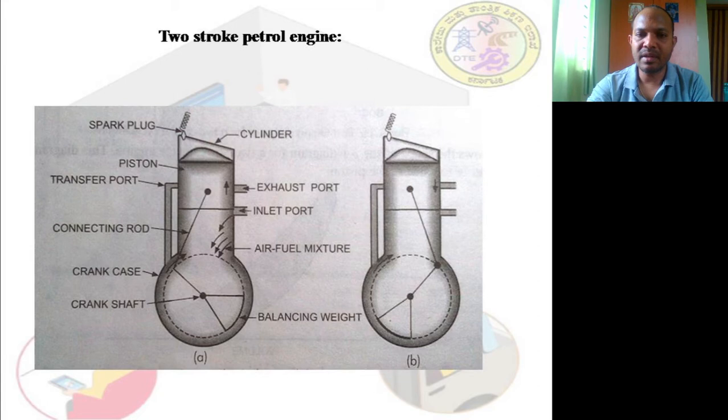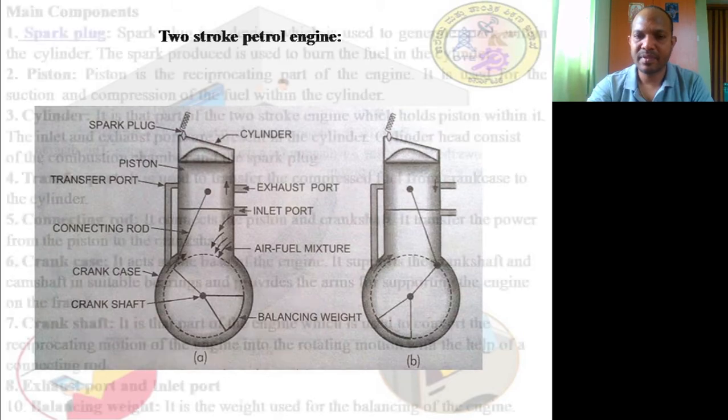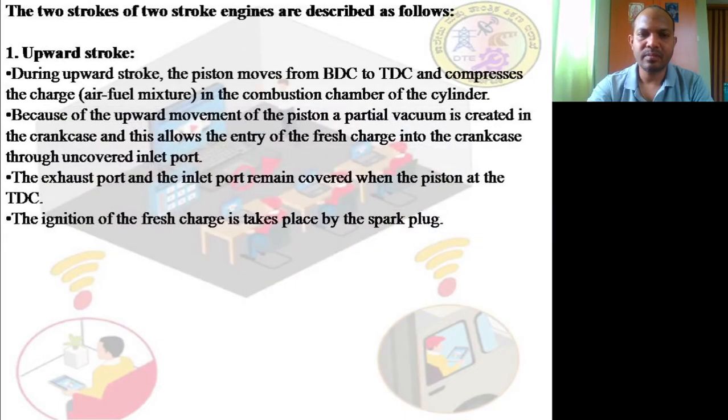Is it clear? While coming back, is it clear? So while going upwards, what happens? Both these ports will be closed. Only the fresh charge will be compressed. Is it clear? The ignition of the fresh charge takes place by the spark plug.